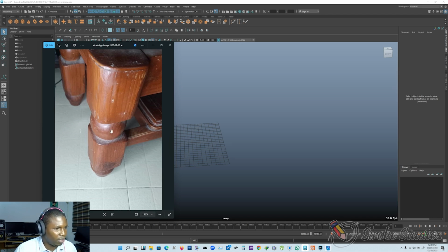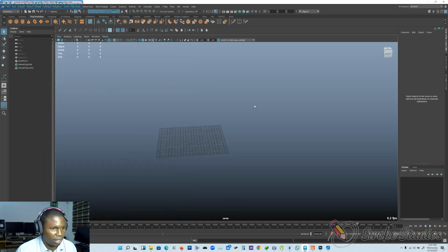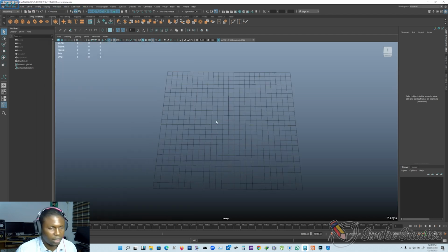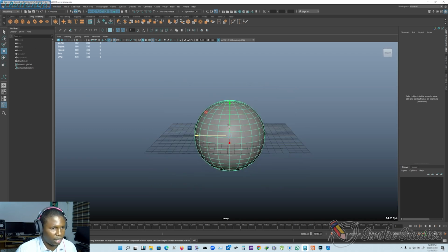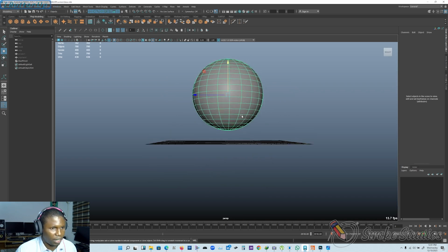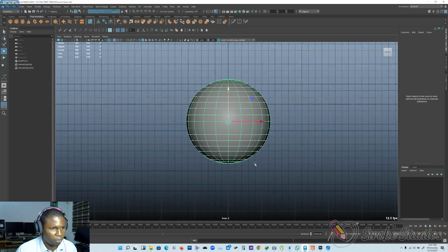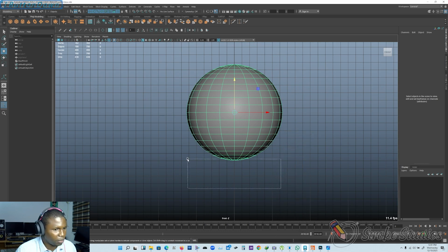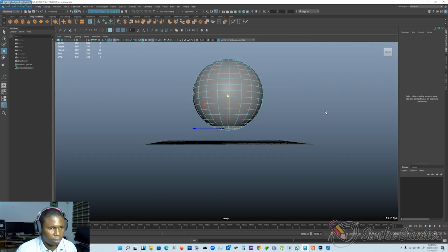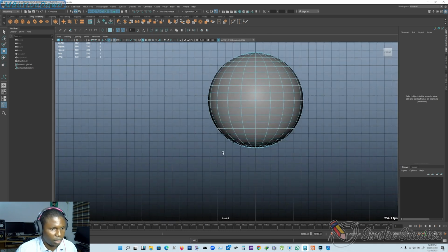We can do this in a very simple way, applying the Circularize option. Now let's see how to quickly do that. Now I can make a sphere in my viewport, right? And with this sphere, I can go to my front view, my side view rather, and select some set of faces and delete this set of faces.